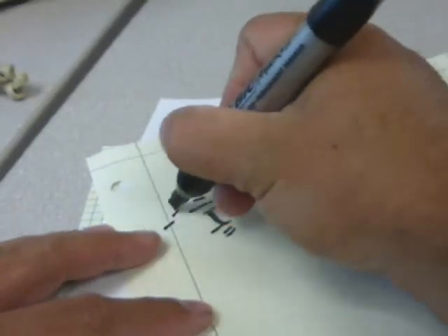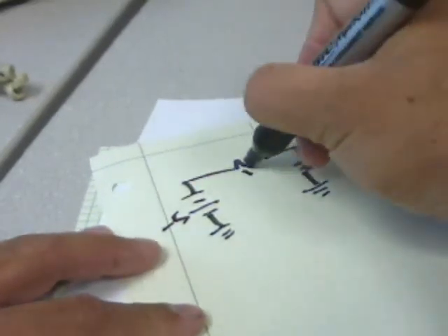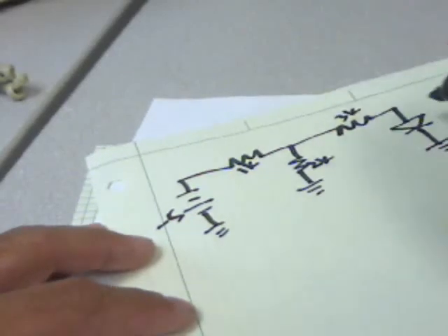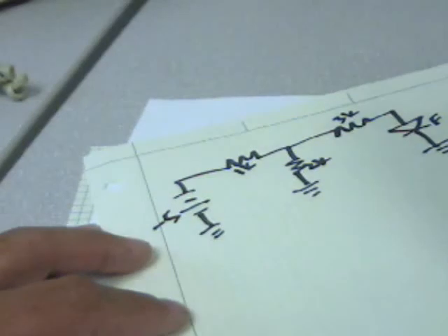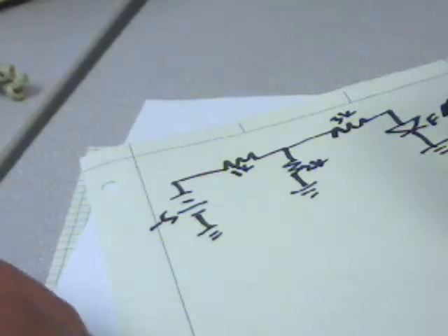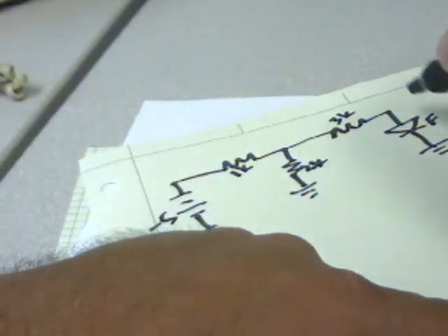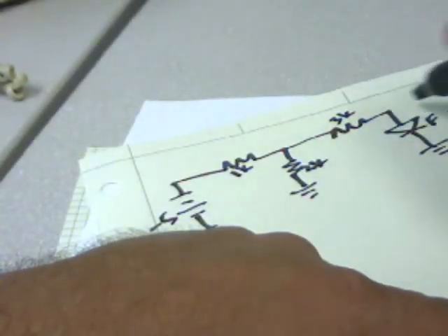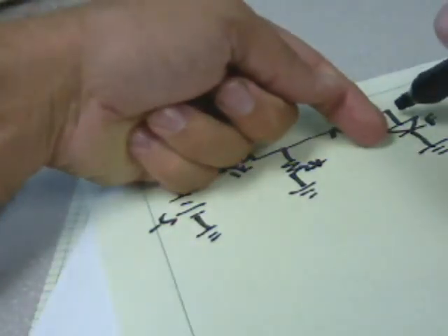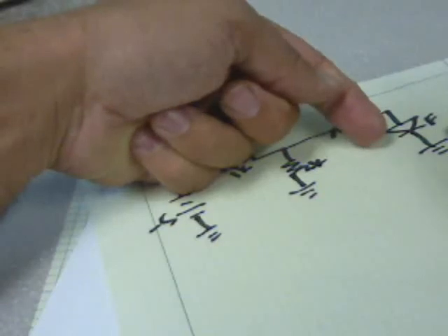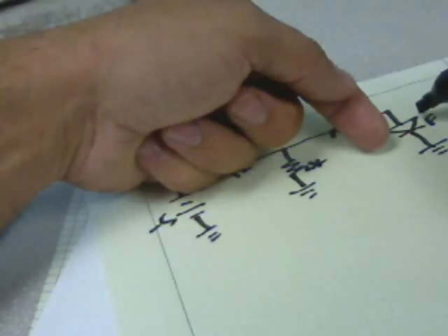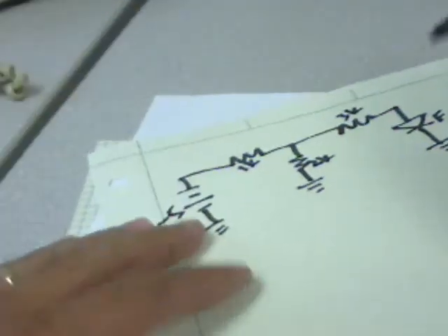Instead of 5 volts, let's say we have negative 5 volts, with 1K, 2K, and 3K. And let's say that we assume it was forward biased this time, because that's the real question. If we can see which way the current's going, and it's obviously going this direction and it's more than 0.7 volts, then we know it has to be forward biased. If it's flowing this direction and it's less than 0.7 volts, then it's reverse biased.